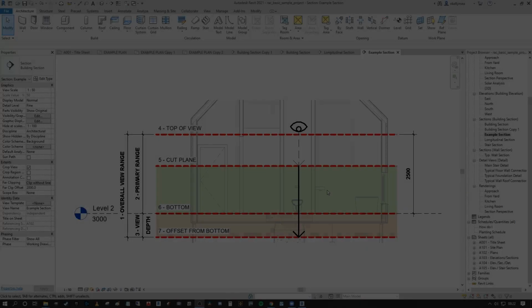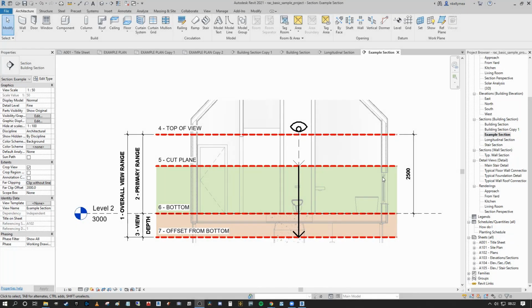Today we're going to talk about view ranges in Revit. Specifically, I want to focus on the major things users actually need to know. My aim is to demystify some of the things that users tend to get confused about regarding view ranges in Revit and how they affect both standard plans and reflected plans, such as ceiling plans and services plans respectively. Finally, I want to cover some additional workflow things that might improve your efficiency as you roll out your view ranges across your Revit project.